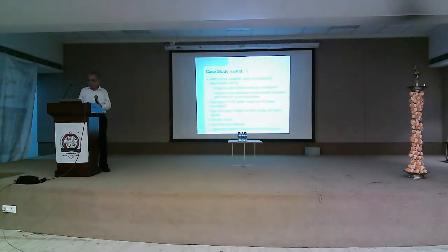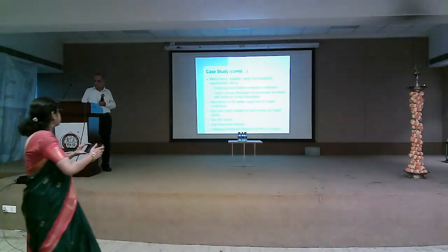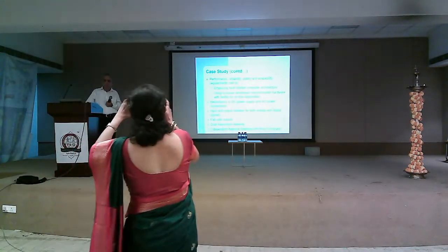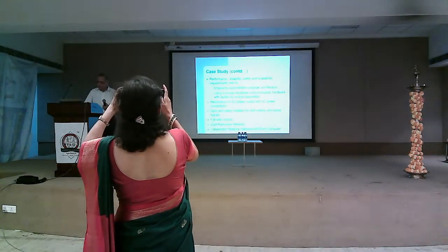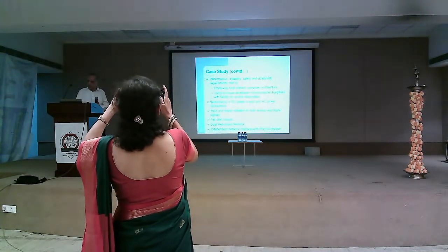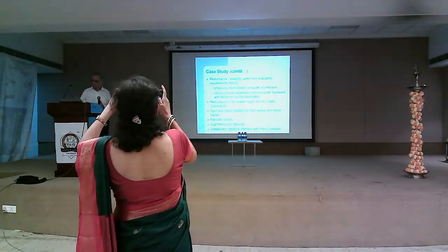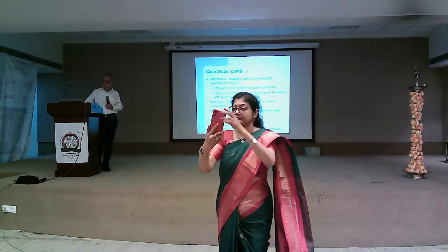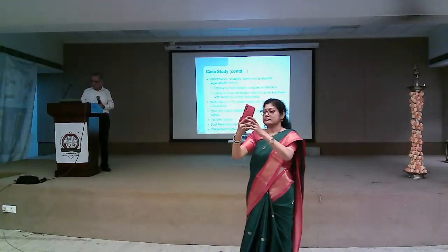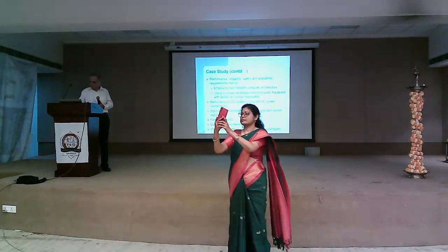So the performance, reliability, safety, and availability requirements are met by the right fault-tolerant computer architecture as I explained, using in-house developed microcomputer hardware with facility for online diagnostics. Redundant DC power supply and AC power connections I have explained. Input and output isolation for both analog and digital signals. Transformer isolation and optical isolation for digital. Fail-safe outputs. Related and independent plant.